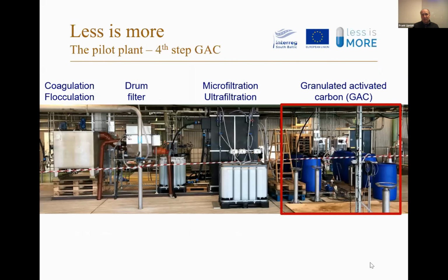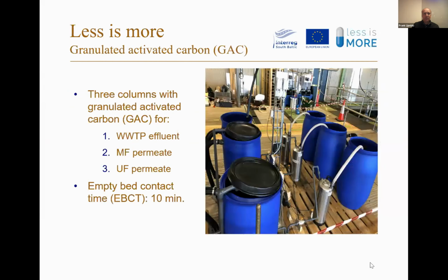And after the direct membrane filtration, we had our granulated activated carbon setup. And we had 3 columns with granulated activated carbon, because in column number 1, we wanted to treat the standard wastewater treatment effluent. Then we wanted to treat the microfiltration permeate and the ultrafiltration permeate. And the empty bed time was 10 minutes. Contact time was 10 minutes.